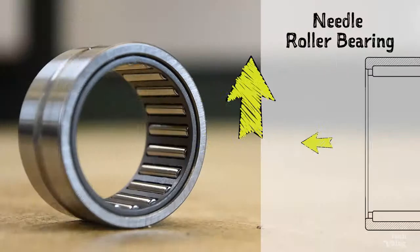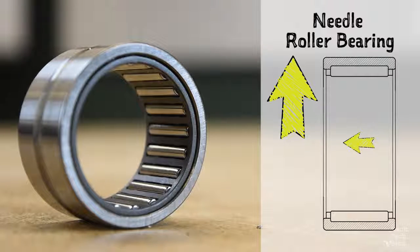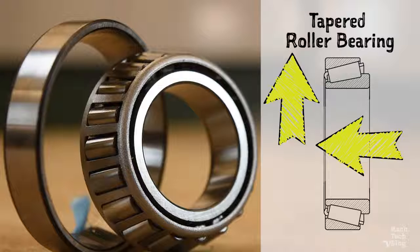Needle roller bearings are similar to cylindrical roller bearings, but their high roller-to-length ratio gives them more load-supporting capacity in a smaller package. They're often used when space or weight is an issue. Tapered roller bearings solve the problem of poor axial load-supporting capacity with tapered rollers that fit into conical races. Although in this case, as with angular contact ball bearings, the axial load must be in one direction only. The ability to handle good amounts of both radial and axial load, as well as a high degree of accuracy and rigidity, make tapered roller bearings ideal for applications like machine tool spindles.